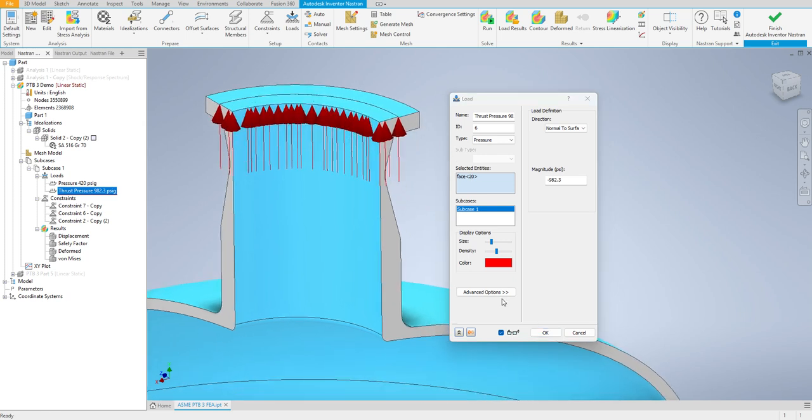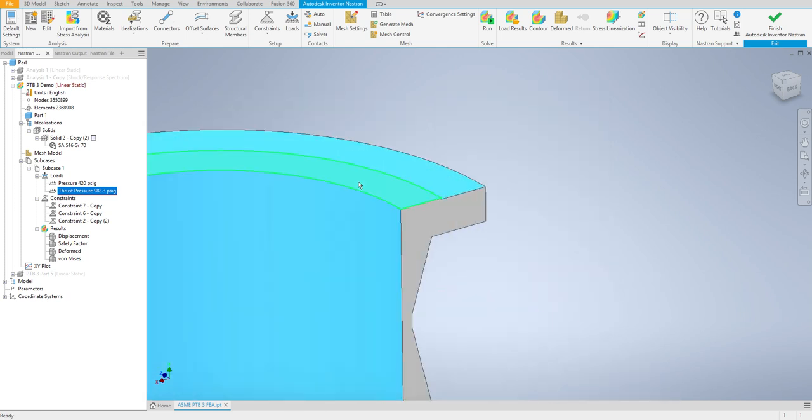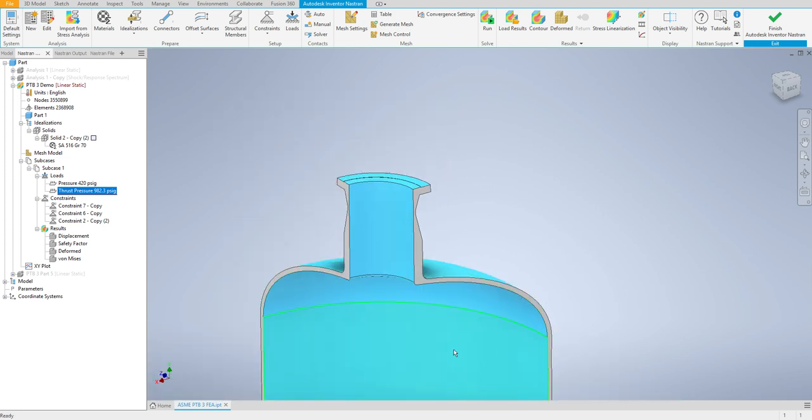As loads are applied as pressure, it doesn't make any difference whether we apply it on the element or on the surface, but it will make a difference when we apply the load as force, because pressure is equal to force upon area. So when applying force, we need to be careful about the area on which we are applying the force.